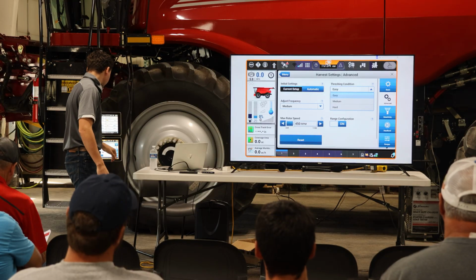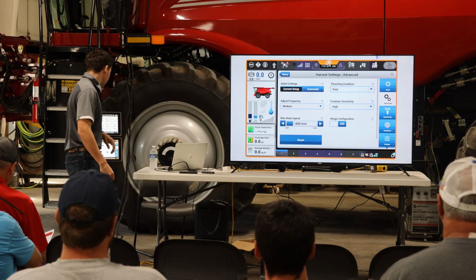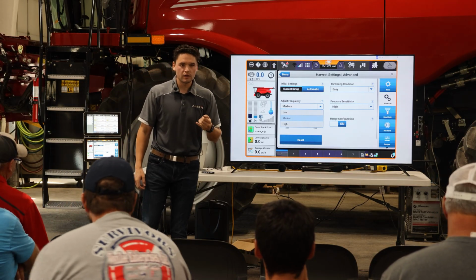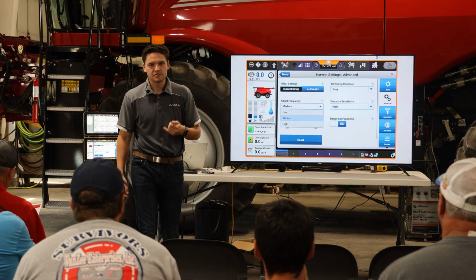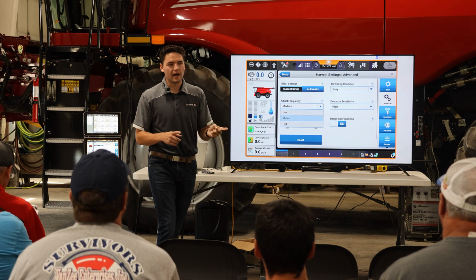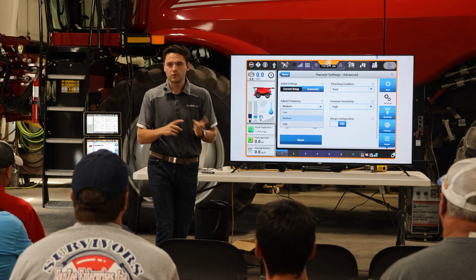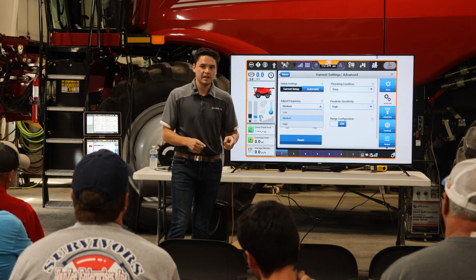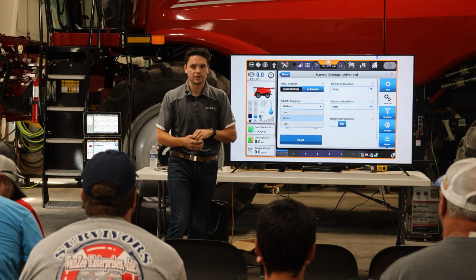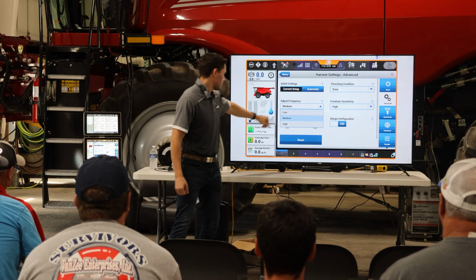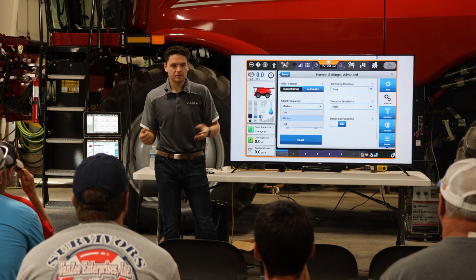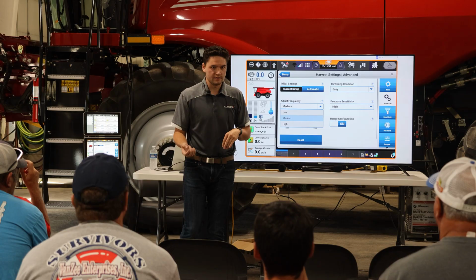It's okay. The next one here is our adjust frequency. And this goes back into, well, what do I look for if it's not making a change fast enough? Adjust frequency is directly tied to how soon or how frequent automation will make a change once it has crested that trigger point. Again, it has to crest that trigger point. So we have low, medium, and high. Low is going to be about 40 seconds, medium is about 20, and high is about 2 seconds.